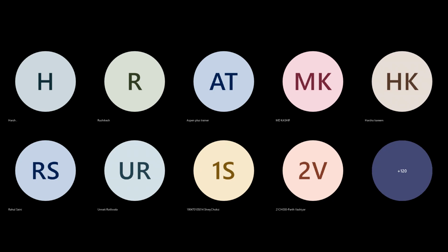मिनिमम सर्कुलेशन लाइन को कंट्रोल कैसे करते हैं? Minimum circulation line generally you have option उसका. Most of the time minimum circulation line, if your discharge valve का line size है somewhere around 2 to 6 inch, then your recirculation line will be 1 inch, and 10 to 15% or somewhere around 20% of the flow rate maximum should be diverted to the recirculation line. उस हिसाब से उसका line sizing करना है.